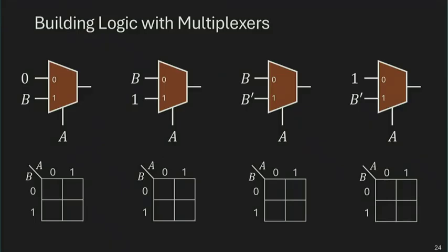And I told you that we can use these components to build circuits. And let's see how we can use them to build some different, more complicated functionalities, starting with some analysis examples. I give you some muxes, and then I connect them to some A, B, and constant inputs. Could you try to figure out the functionality of the first gate? I'll give you half a minute to work on that exercise. Try to recover the output behavior as a Boolean expression in terms of A and B. If you have more time, feel free to also work through the other examples.